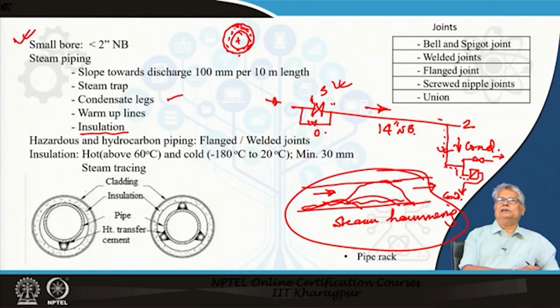And in fact, between the aluminum cladding and the glass wool, you usually have a chicken net to hold the glass wool together. So, that is the insulation, and you must have insulations. This is the typical insulation in large industries. For short lines, as you have in the laboratories, you may use other options also, other insulating materials, but that is much less common in industry.